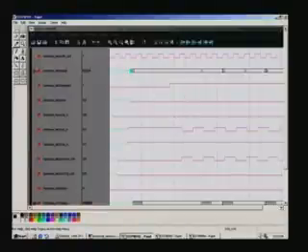Going to the waveforms, here I will first read out before zooming. We have a clock out here, and this is the clock signal operating at 100 megahertz, and this is the address that we have. It may be a write address or read address here, depending upon this RWN control. If it is 0, it means write, and it is right now in the write mode. Because at the start we want to write some data, and let us see what data we have. We have the same data in all files, and the same data is being rewritten.